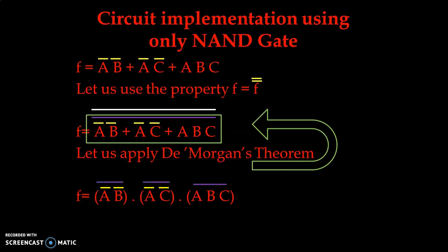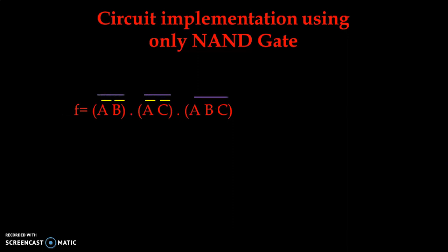So now we have converted our original switching equation like this, and we have a whole bar that we have to keep as it is. This is now the final converted Boolean expression or switching function from which we have to implement our logic circuit using only NAND gates. Now we write again our equation, the switching function.